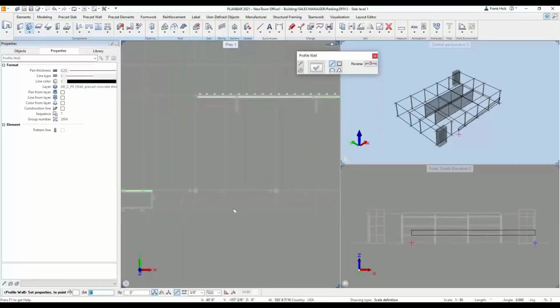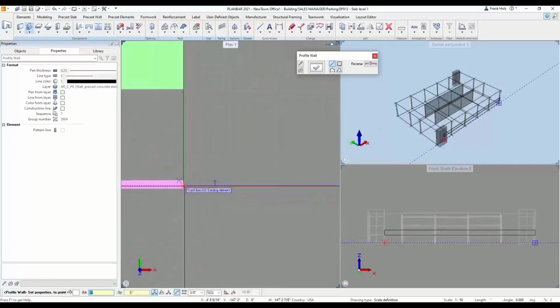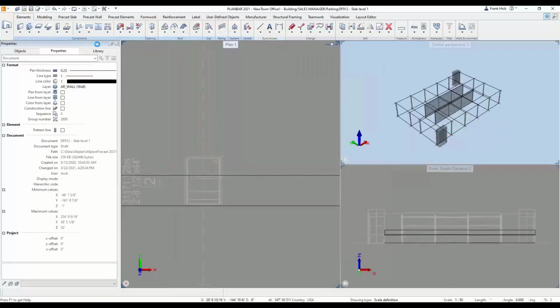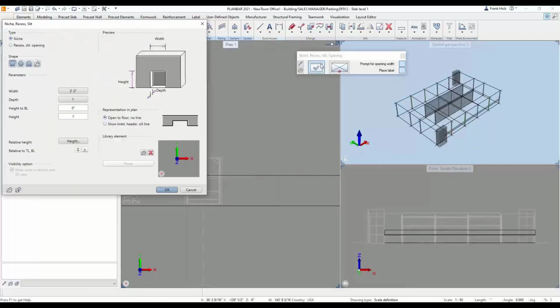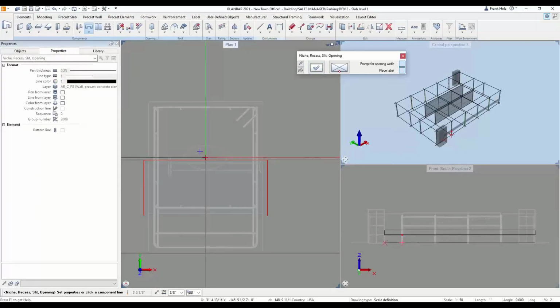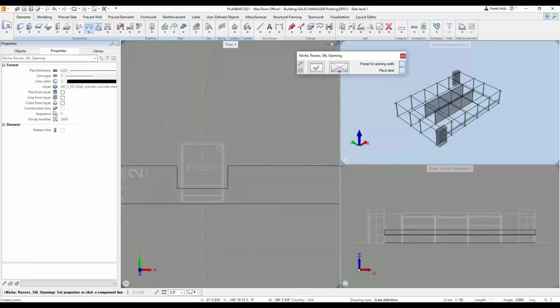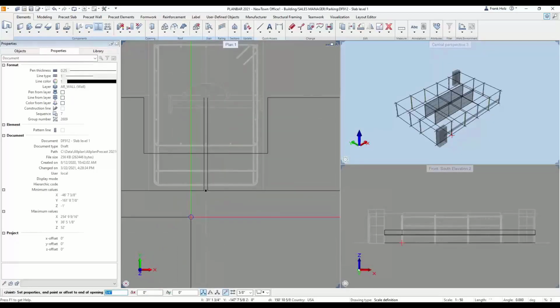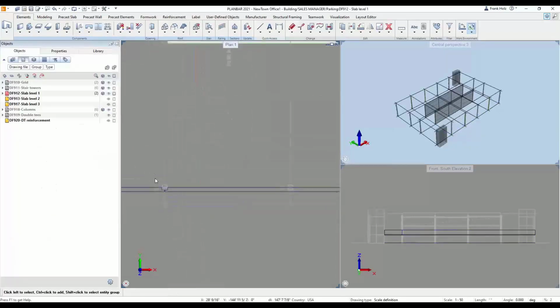All right, so I'll draw my first wall from one column all the way to the end here. And now we need to notch out around our columns. So for that, we're going to use a niche. This again is parametric. I enter the width, the depth, the height, so on. And then it's just a matter of selecting it in my 2D model. Again, with the joint, it's parametric. You select right in your drawing where you want to place it. You confirm some parameters like the width of the joint, the position of the joint, and it will hold back that opening for you. And even though all of these things are parametric, there's nothing in here that doesn't look exactly like doing it in CAD.